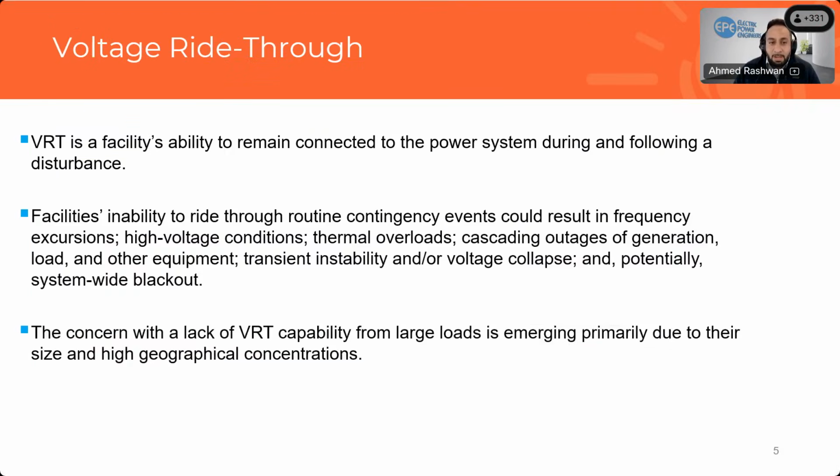So jumping ahead to voltage ride-through. This may be some review for some folks, but we want to set the context before talking about the requirements. So VRT is the ability for a facility to remain connected to the power system during and following a disturbance. And I'm making this point specifically because if you talk to the load communities, not from the utility perspective, but from the actual large load developers, to them, voltage ride-through means that their processes continue regardless of the grid's condition.